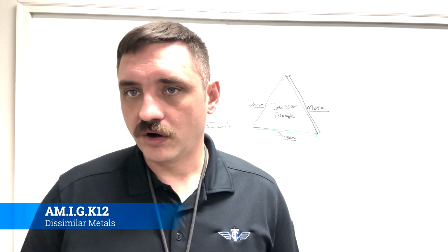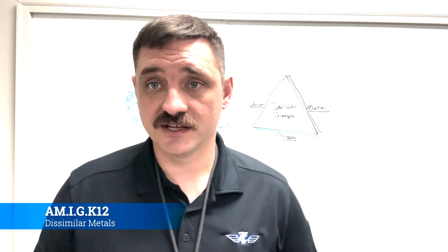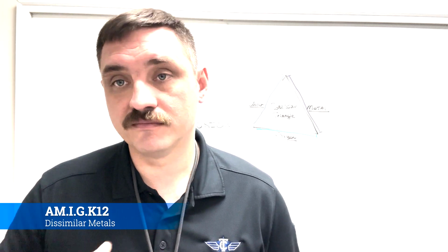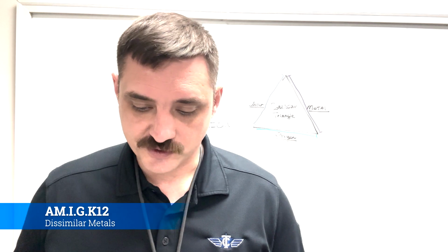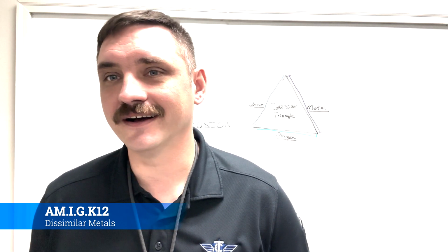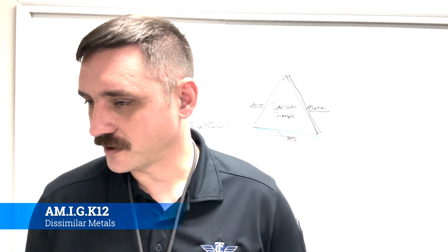Now, almost all of these dissimilar metals have some sort of barrier in addition to the zinc chromate that will keep the metals apart. The separating materials may be metal primer, so that's what the magnesium gets: we prime it before we paint it. Aluminum tape, you'll hear go fast tape, or speed tape.